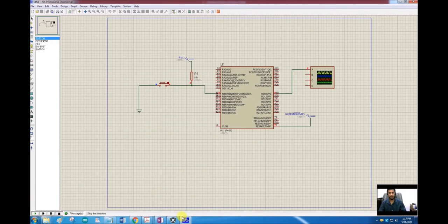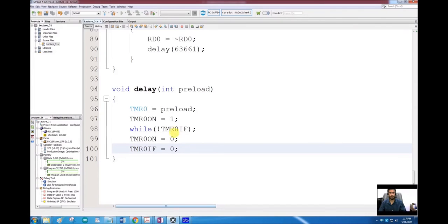So how much better is this approach to create a delay using a timer as compared to what we were doing before using a for loop or using the nested loops in assembly language. So using timer to create a delay is very effective and very precise up to one count of this timer. We will use interrupts with timers in our next lecture.